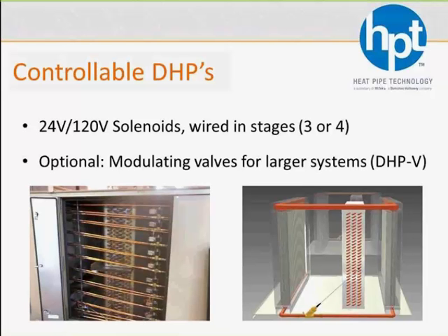Horizontal fins are fine when it comes to just air-to-air heat recovery, but when you're talking dehumidification, it can lead to that condensation not running off the fins as well. So if we've got 4 rows or a lot of outside air, or even modulating airflows where the velocities could get down, you might actually see a buildup in condensation that won't go away.